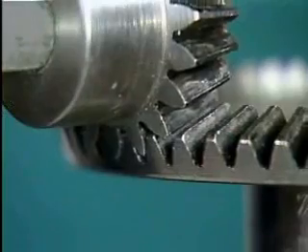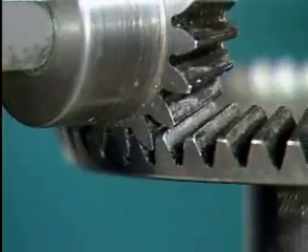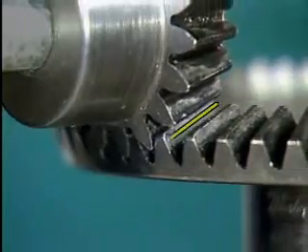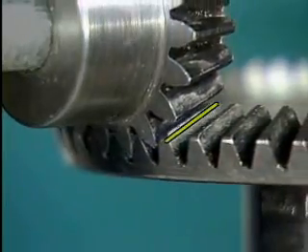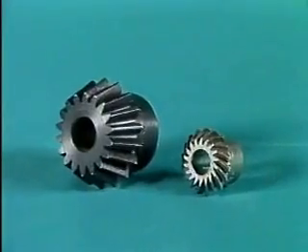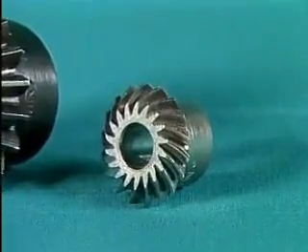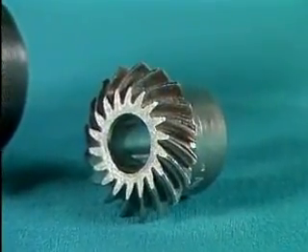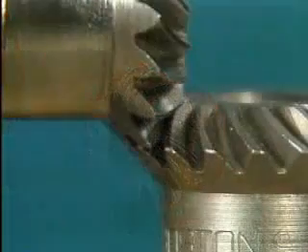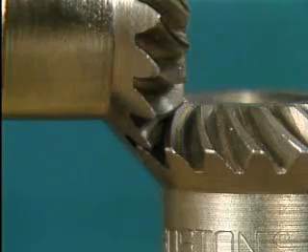Now, if you were to closely observe a spur or bevel gear set, you would see that the gears mesh across the entire gear width at the same time. When gears mesh in this way, they may produce a lot of noise. In order to reduce this noise problem, and to enable the gears to carry greater loads, some spur and bevel gears are made with their teeth twisted. This design increases the surface area of the teeth and allows the teeth to engage more gradually.